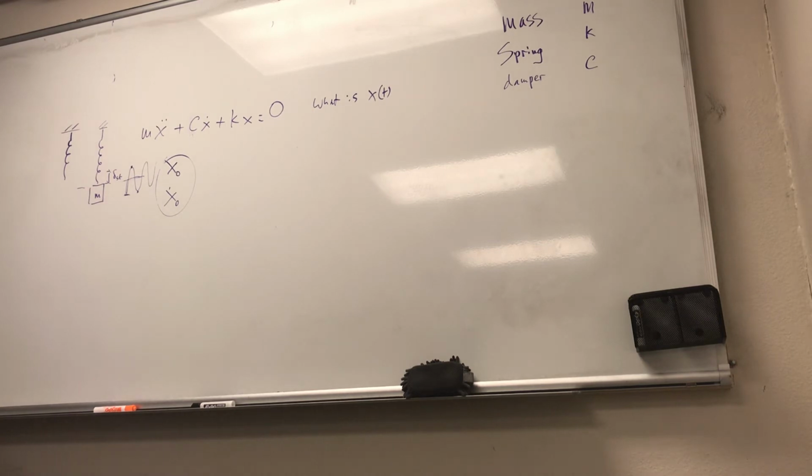And in dynamics, the general form, F equals ma, typically yields a constant acceleration or acceleration that just changes with time. But here, it creates accelerations that change in sign all the time. So at one time it goes this way, then it brings it back. That's why it always points towards an equilibrium position. That's why I said this is a very special case of a vibrating system.